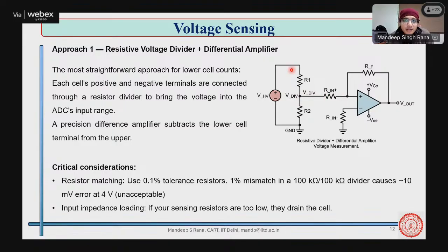the next connection. For example, there's a current flowing through this particular path and another current flowing through this particular path. It causes your voltage balance to end up in a zone you did not plan for, because the whole study of the voltage divider is based on the current flowing through in series, with no current going in this path. Impedance matching is very important. So input impedance at this site should be infinite and it should not take any current. Those are basic precautions we already take when implementing an amplifier-type circuit.